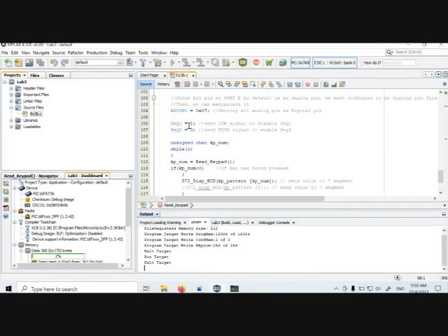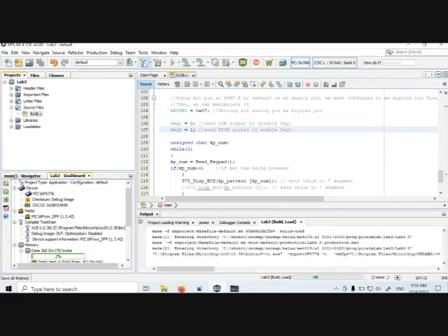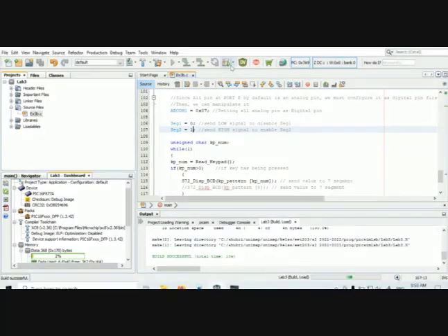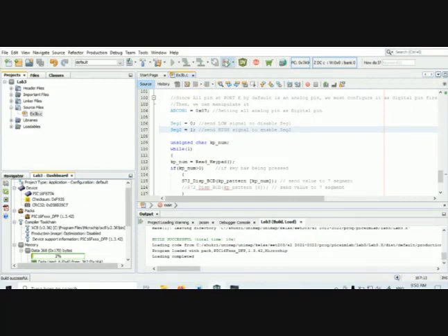So right now the code is enabling the first segment. So you can change it. Make sure that you stop the simulation first, and then you repeat. Start repeating by building. Any changes made to the program, you need to rebuild, and then after that you debug. It will be success, and then go to debug.